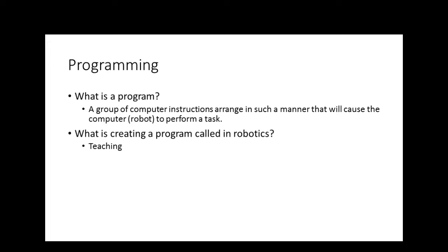And that's what we're doing. So what we're doing basically for programming, and this is what we'll start out with until we get to really high level stuff, is that you literally take the robot and you jog it to where you want it to go, and then you tell the controller to remember that point. And that would be teaching, right?